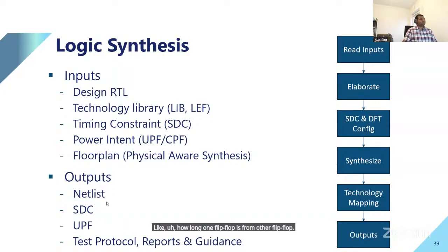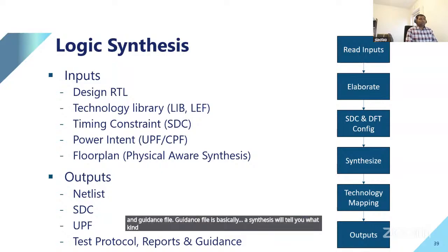And what it generates for you is a synthesized netlist, SDC file, UPF, test protocol if you insert test here, and a guidance file. The guidance file is basically where synthesis tells you what kind of optimization it's performing, whether data optimization or clock optimization.